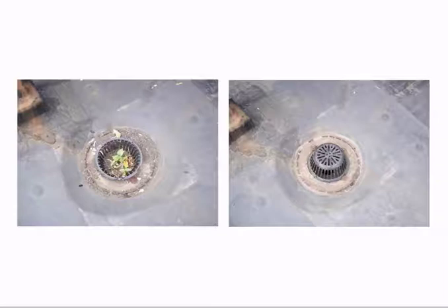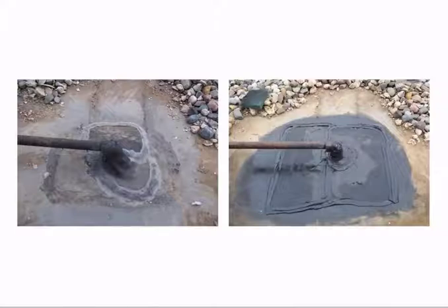Here we have a before and after, but is this a green roof, or was that intended to be a green roof? Looks like someone's going to enjoy a salad for lunch. I see a lot of that. People will flip that drain basket over, thinking that they're eliminating stuff going down in that drain. Well, it's the opposite. Once that basket fills up, the water can't get through it. So keep your baskets upright the way they're intended to, and do some roof maintenance a couple times a year, cleaning those out. Super easy fix there.